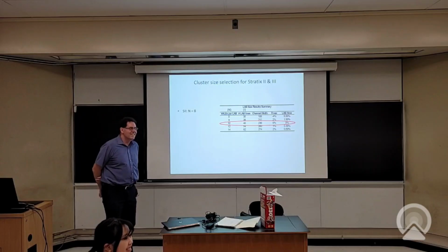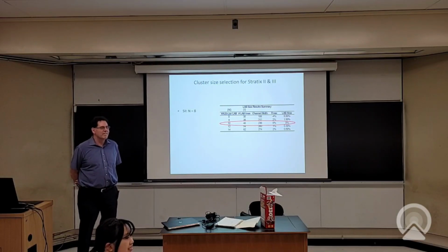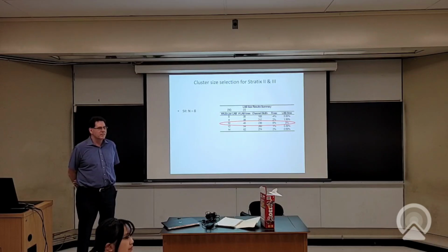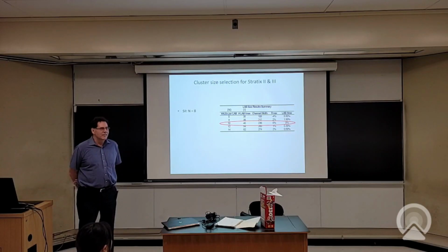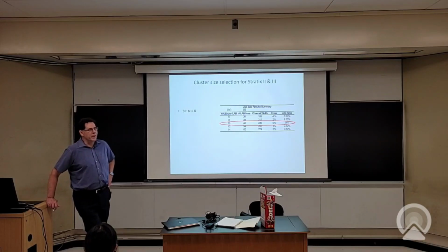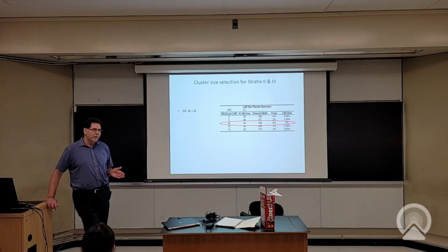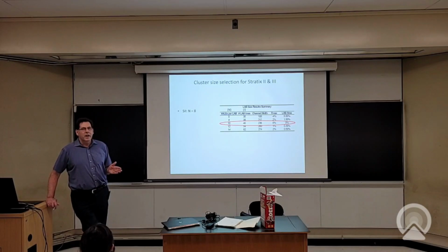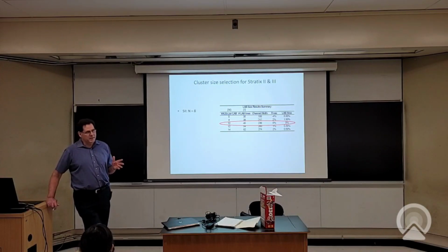So it seems like it's a question of architecture. Could we make the routing flexible enough that we don't have to use these weird block configurations for this specific function, and do something way more useful? Yeah, and there are architectures that build actual muxes in their logic block, where they'll have a mix of say LUTs and muxes, because they'll say, well, there's a lot of mux functions, so I don't want to use just LUTs to do muxing, I'll just build muxes. And there are architectures that have been built with that. And they're not unreasonable, but Xilinx did some of that, and they've now moved away from it and just said use the LUTs. And the basic reason is adding all the pins to connect to the muxes is still expensive.